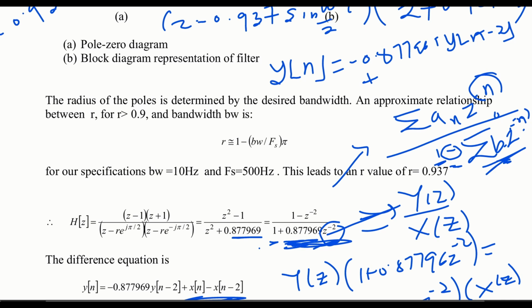Well, the zeros at the top, we have 1. You see here, there was no 1 here. So at the top we had 1, and we can represent it in the inverse z transform format. So 1, according to the inverse z transform, will be x of n, because it's a zero at the top, minus this, which is z raised to the power minus 2, so this will be x of n minus 2. So that's the whole procedure of using the diagram.